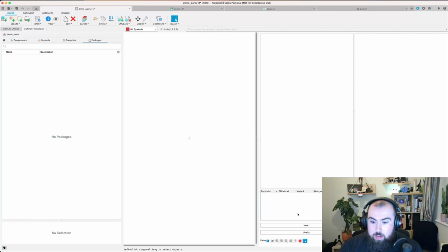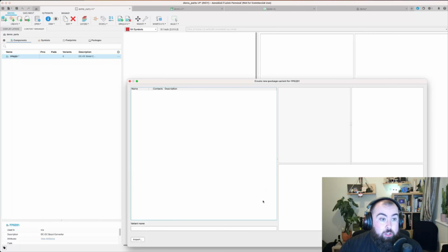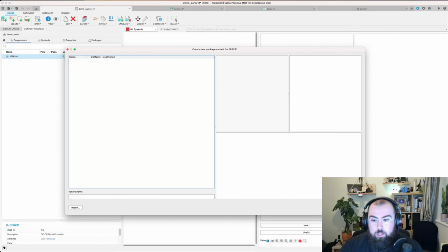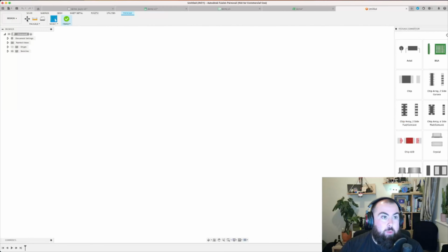So make a new package. We're on the component, in context of the component, so we go down here to this section. We'll click new and say add a local package, and it'll pop up like this. Oh, sorry, actually, that's wrong. My mistake. That's how we associate one that we've already uploaded. We need a new package. We go up here to the top left and create new package.